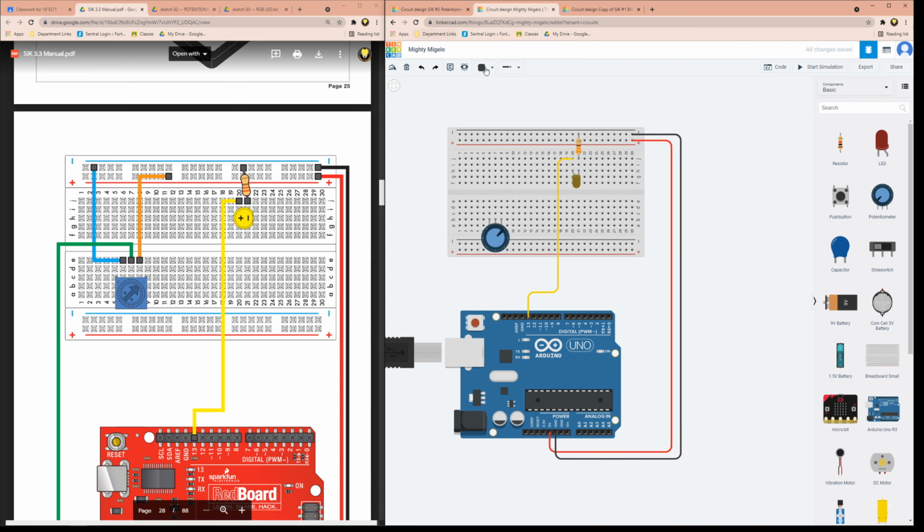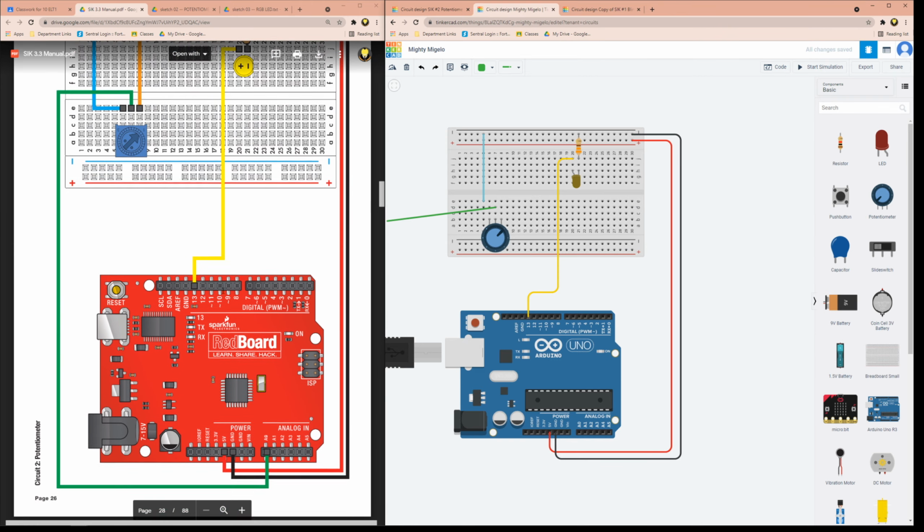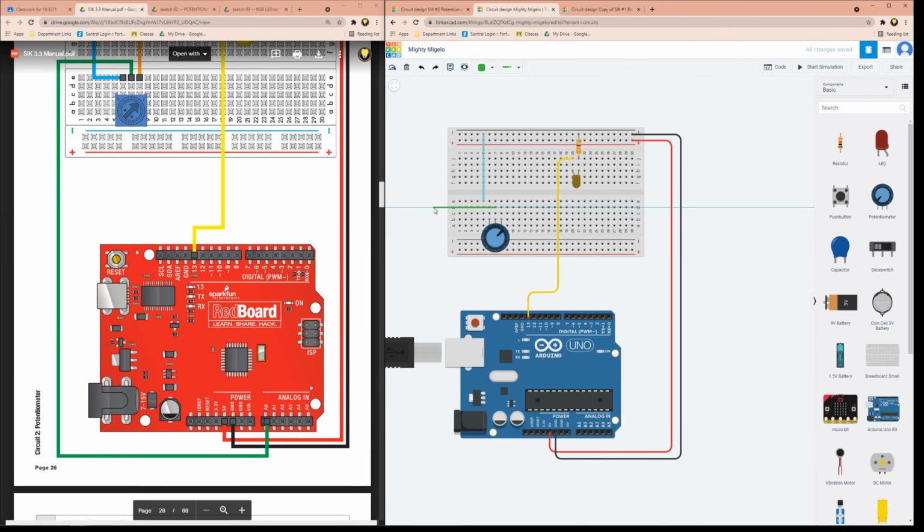And then we want some colored wires. We want this turquoise color over here, so our potentiometer, we want this pin over here connecting to that. We want our green pin connected to, I believe in our diagram over here, our green pin is connected to A0. So we'll just go out here.